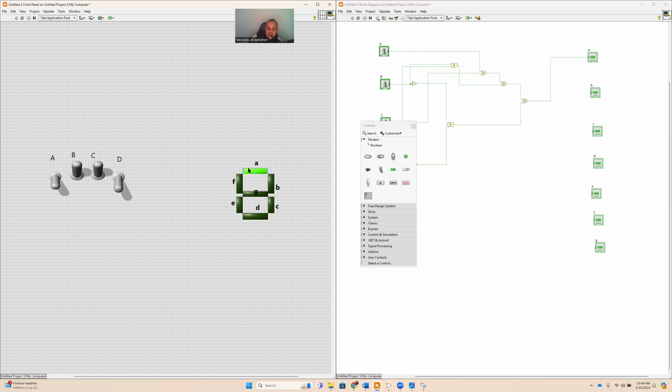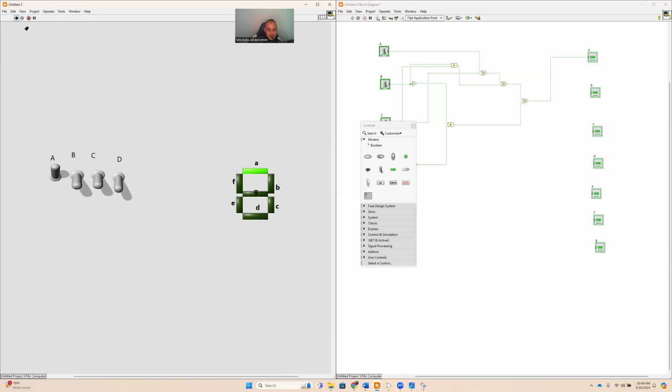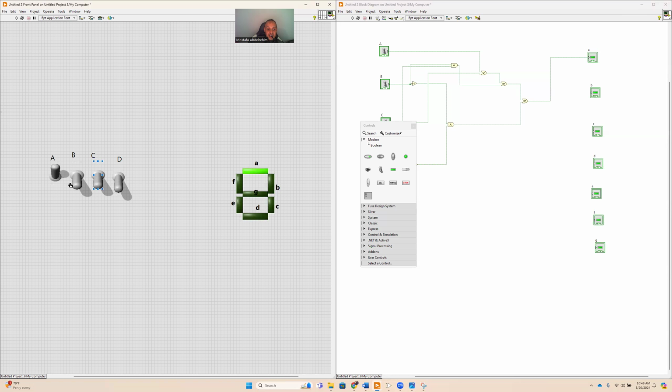That's good. For number 7, it should be on because 7 is A, B, C. 7 is 0, 1, 1, 1. A is on. 8, all of them is on. So 8 is 1, 0, 0, 0. Yeah, that's correct. 9 is 1, 0, 0, 1. It should be on because 9 is A, F, G, B, C, D. Okay. Yeah, so we did implement A correctly. So you're gonna do exactly the same for B, C, D until G.